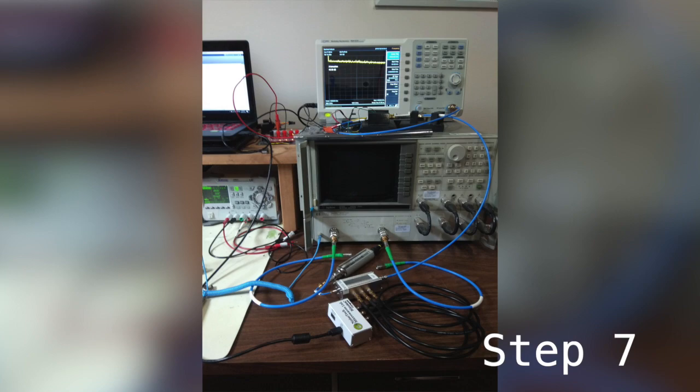What you're going to do is start off with the noise source off, collect several averages on the spectrum analyzer, and save the power trace. And then in step 8 you turn the noise source on, and you should observe a small or moderate increase in the noise floor as seen by the spectrum analyzer, depending on which noise source you're using. If the noise figure of your preamp is 5 dB and your ENR is 15 dB, you might expect it to increase by the difference between the two approximately, just to make sure everything's connected correctly.